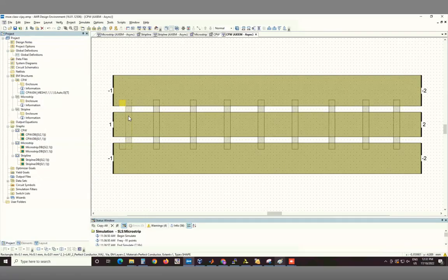It's on this dummy layer, or interface between these two dummy layers, and it's going across. Since they're all overlapping, you have the ground plane here, then this via patch which goes up, then this metallic patch which goes sideways, and then another metallic patch which comes down. So what I'm saying is that all these patches should be connected by a horizontal metal plate.